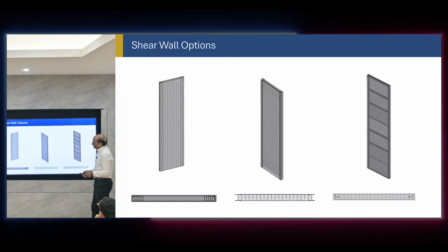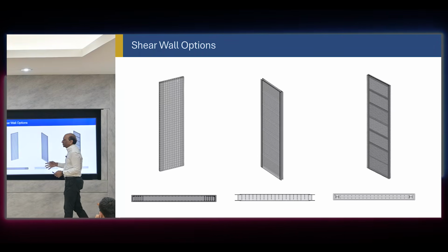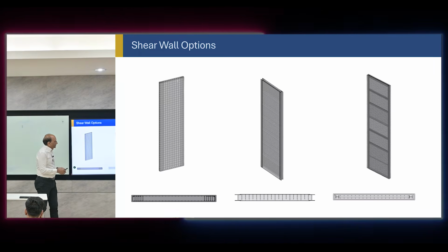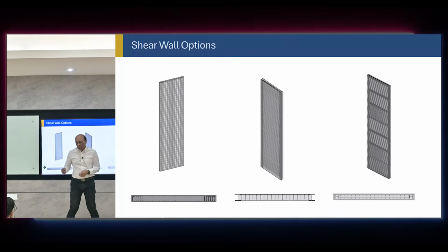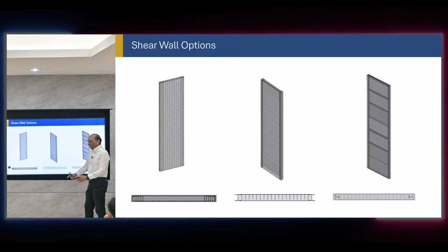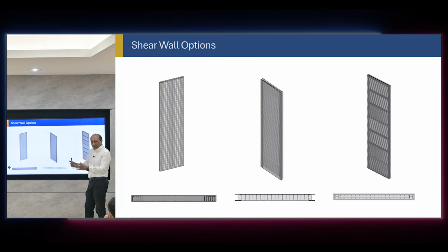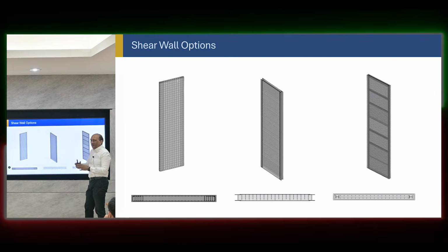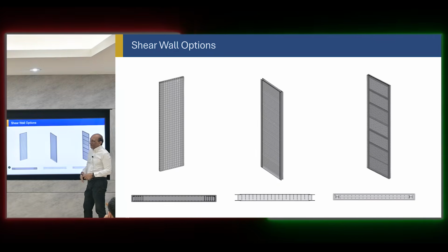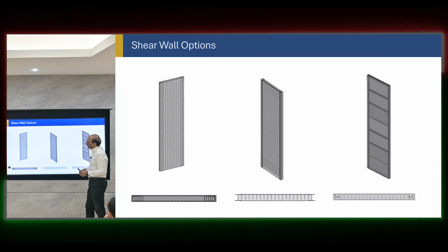Then shear wall. Like I said, elevators are normally shear walls, but not only that, we also add other shear walls, and their design will also control the speed of the construction. Normally, the core wall or the shear walls are made before the building, and the building then follows and connects, because they are formed very quickly. So making the shear wall as fast as possible and as economical, as thin as possible, is very important.